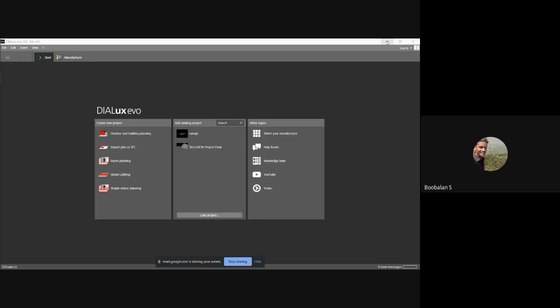So if you have a simulation based project, instead of physically placing the bulb and going under the lamp to check with the lux meter, right? I am going to place the same civil building's entire geometry into my software environment, copy that entire geometry values over here, and place those different lights in this software. I am going to measure that flux with the help of the software, so we check without the help of the physical lux meter.